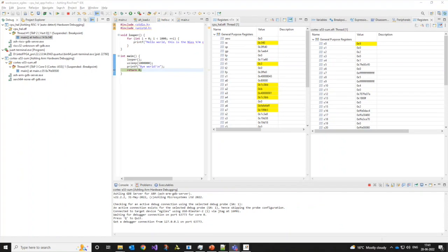However, with Nios 5, given that it's a RISC-V architecture and RISC-V has a growing ecosystem, you have the option to use any other tools, toolchains, and IDEs of your choice that would work with any RISC-V processor. They would also work with Nios 5. One of the other differences is that in the Nios 2 family we only had 32-bit cores, but we have plans for 64-bit cores for Nios 5. And also, Nios 5 cores are free of cost. Some of the differences. Okay, thank you.